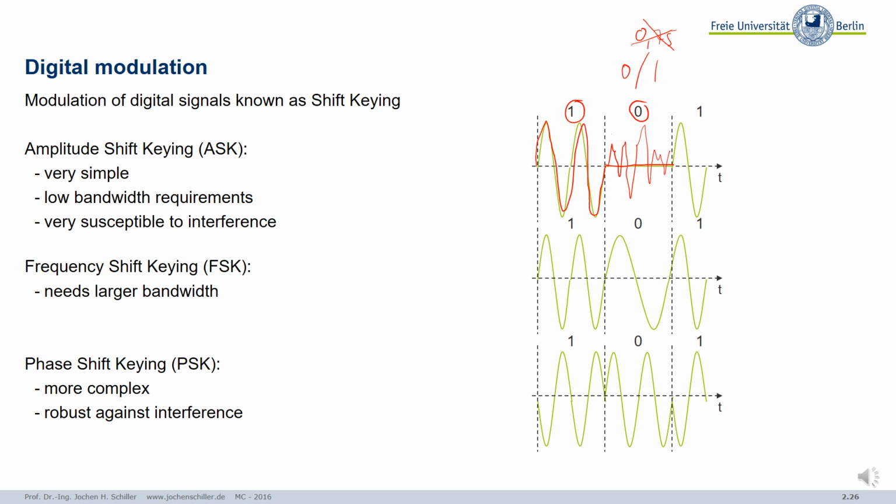Frequency shift keying, basically, you use one frequency F1 for 1, and one other frequency F0, for example, for the 0, and then you basically change the frequency. Higher frequency, lower frequency, higher frequency, for example. So you code your bits into the frequencies. That's, by the way, what you hear in a classical analog acoustic way for the old fax devices, when they start sending their different tones over the classical analog telephone line.